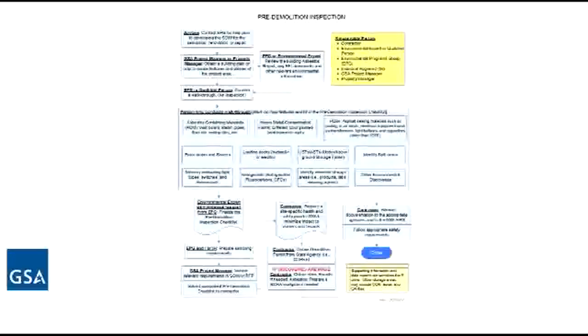We will contract for individuals or do a walkthrough ourselves, in particular looking for asbestos issues, but also looking at lead paint and other environmental issues associated with it. We may be doing some sampling on it. There will be abatement plans developed, contracts will be let. Then you will probably step in at that point and be doing the abatement or the demolition on it.